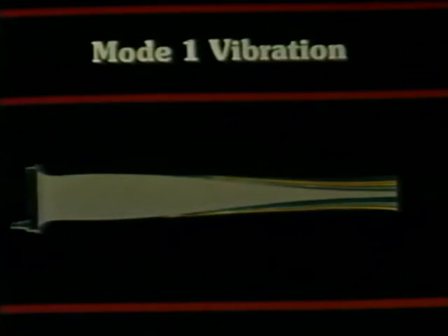If a blade goes into resonance, it will be in a condition called a mode. When it vibrates in a mode, higher than usual stresses occur at the points where the blade is bending. These points are known as nodal points.